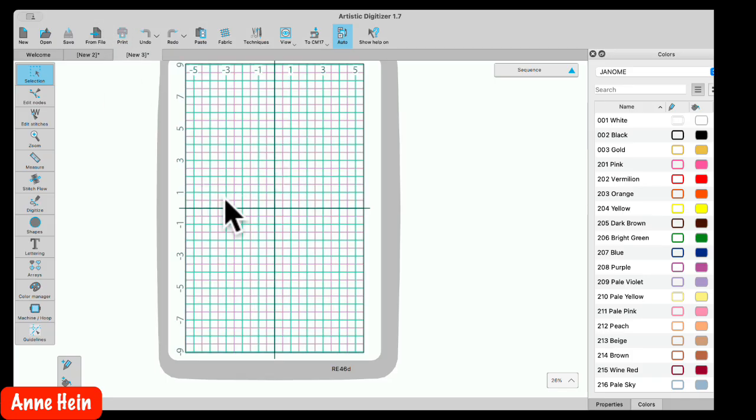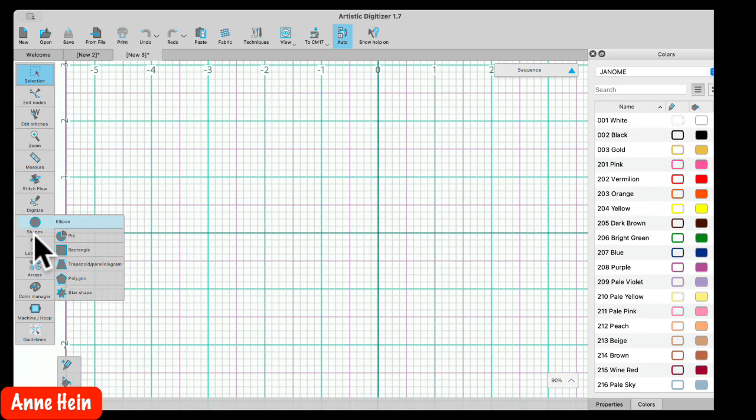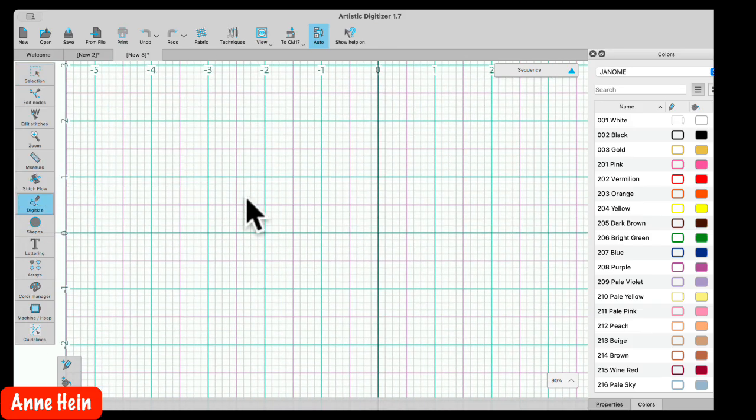So sometimes when you're working with the outline shape tool, if you touch the Alt key, or on a Mac, you hit Command, and I'm going to do Shift because I want them to be on the line. See how it'll snap to those lines for me while I hold the Shift? I'm holding Shift to get a straight line, and I'm holding Alt on my PC or Command on my Mac.